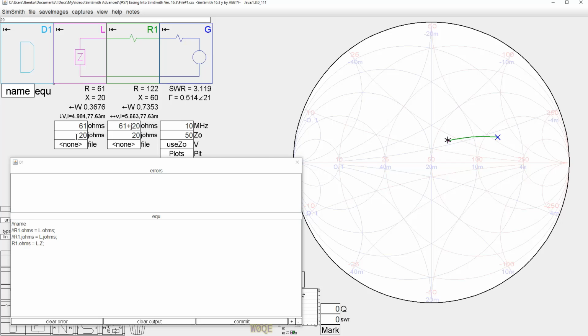Notice that this value here is kind of weird. I set this to be, this 20 is from before. We're no longer updating it, so really this needs to be 0. It won't ever get updated when I change this, but it was a holdover from a data value that was calculated, and that's one thing in SimSmith. If you calculate a value for a parameter field, and then you take away what was writing that, it keeps the old value there. And that's burned me a few times in the past, but it's the most logical thing to leave behind, which was what was previously there.